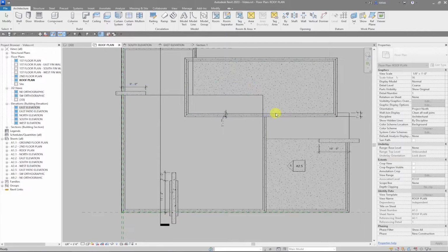Half of 45 is 22.5, which would be 22 feet 6, and half of 10 is 5. So 6 plus 5 inches is 11, so we get 22 feet 11 inches is half the distance. We are going to say, let's just say 22 foot 6. Because again, if we keep the distance shorter, we'll ensure that we will have a steeper slope. It might be slightly over 1/4 inch per foot. So that's 22 feet 6, or 22.5 feet.